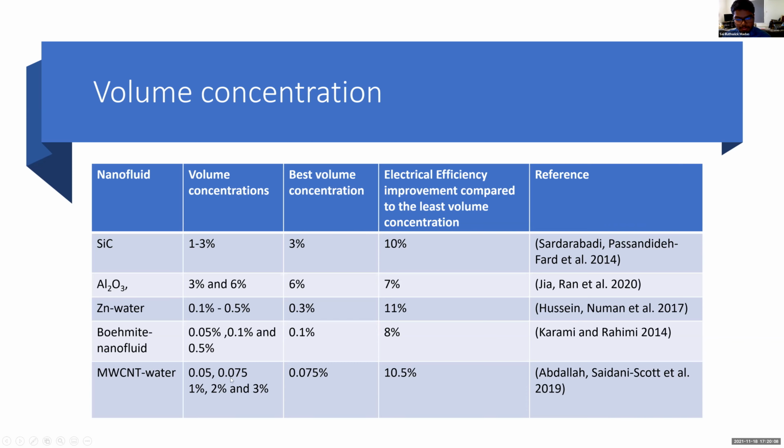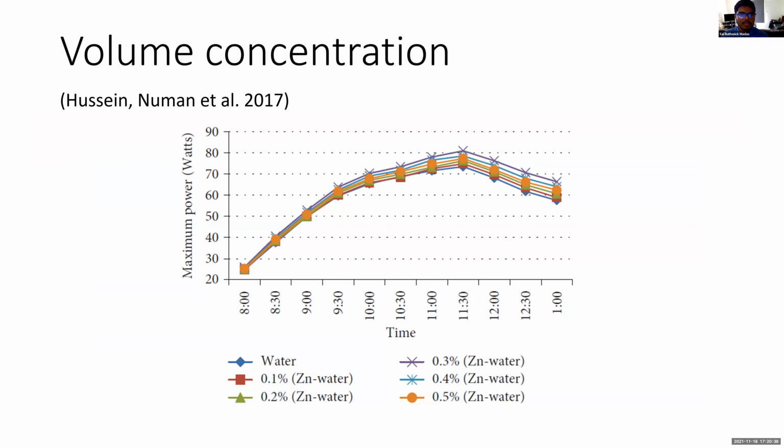They stated that within the tested range of volume concentration, the particle with high concentration was not the best performer. This is because there is a possibility that although nanoparticles have high thermal conductivity, they have low specific heat, which upon high suspension into the base fluid will actually kill the heat carrying capacity of water. So particle volume concentration selection is a parameter needing careful consideration for better performance.